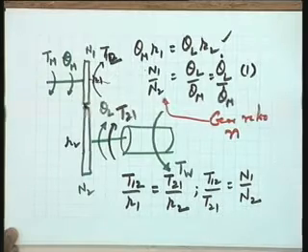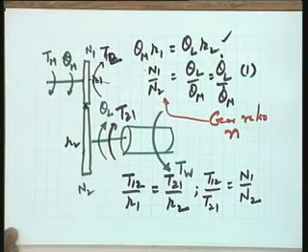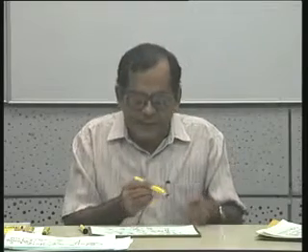The torque available at the load shaft has been increased by a factor of 30, which is the inverse of the gear ratio n. So the gear train provides the required torque magnification and corresponding speed reduction, and how you fix the gear ratio naturally depends upon the characteristics of the motor and the load. These two units will dictate the value of the gear ratio, and accordingly you will design a suitable gear ratio for the system.